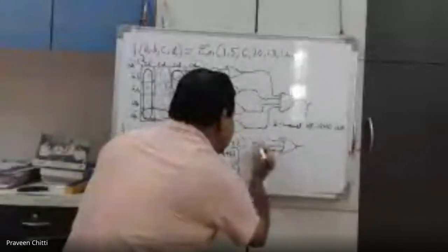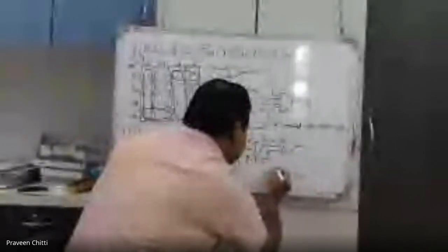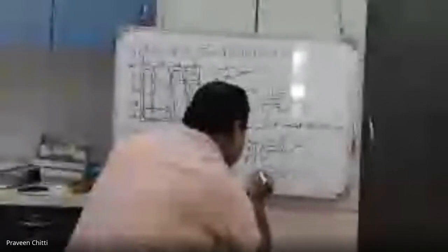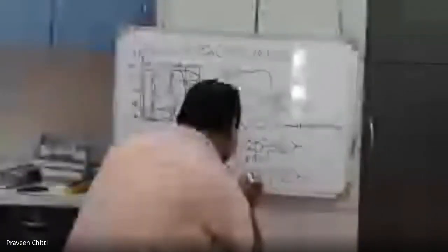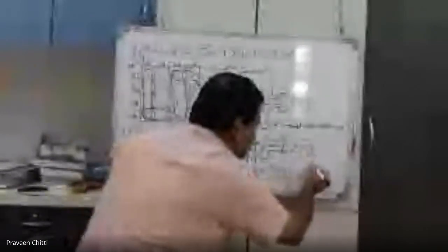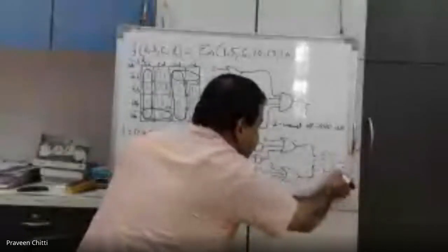And here the inputs for these 2 AND gates are A bar D, BD, right? Similarly, I will have one more gate here, that is C bar, and then I need 2 more AND gates with A B bar and B D bar. And these 2 what we have got can be given to the AND gate, and you will get the F.